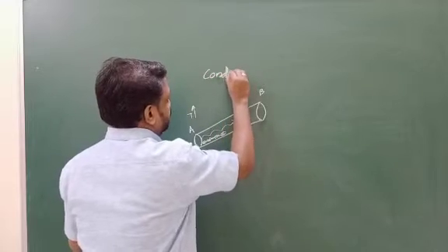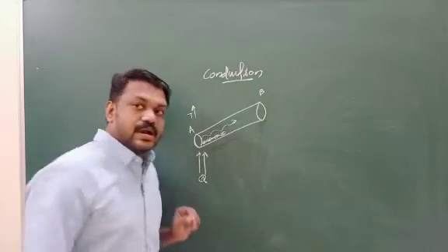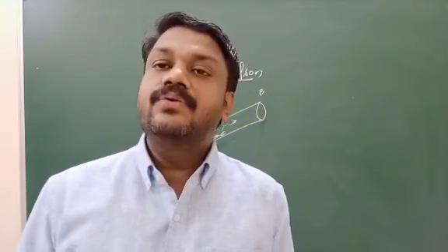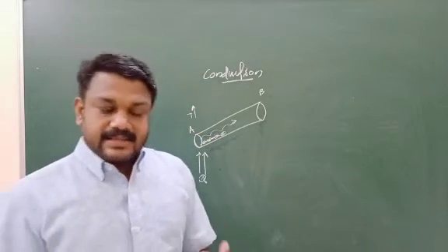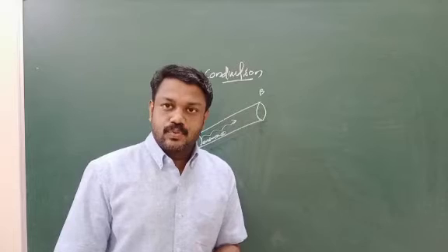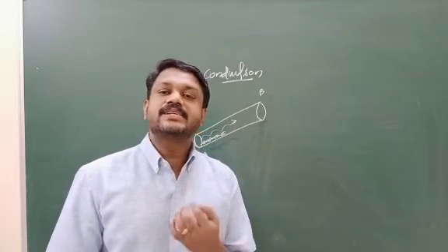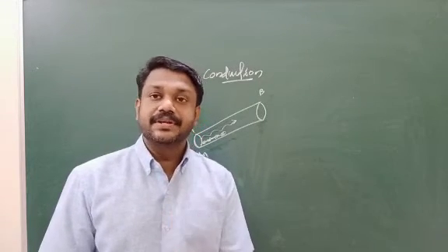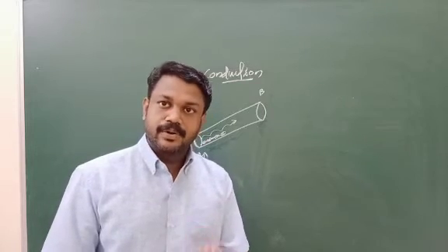So conduction is the mode of heat transfer found in solid material. The mechanism is, as the high energy is absorbed, the solid particle starts to vibrate, then it collides with the neighboring particles, and through successive vibrations and collisions, heat energy can be transferred from one point to another.